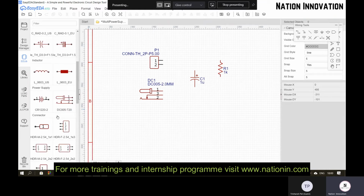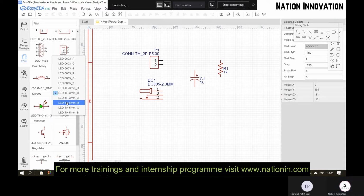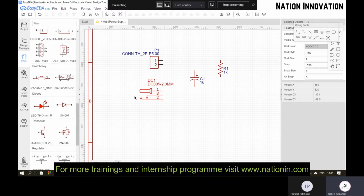And for that, we are connecting LED. This is our LED. You can take any color and it is 3 mm and 5 mm. So I will take a 3 mm red color. Again rotate the LED so that your cathode is facing downwards. Now the connection has to be made.